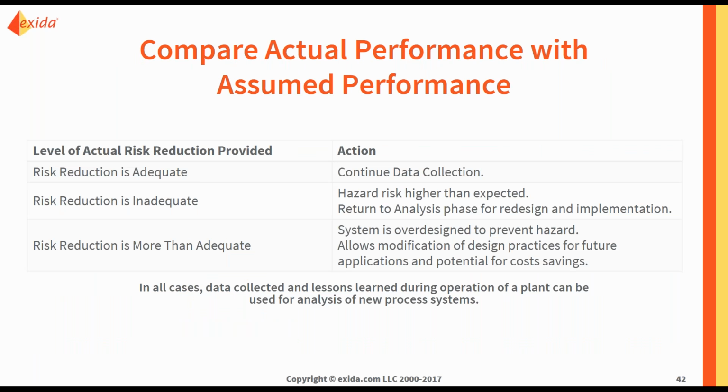So the reason life event recording is important is because you want to compare your actual performance with your assumed performance. As I said in the analysis and realization phase of the life cycle, a few assumptions are made that hopefully apply to your site. But if they don't, you want to know that as soon as possible. If you collect enough data and you find that your risk reduction is adequate, then great. This is the perfect scenario.